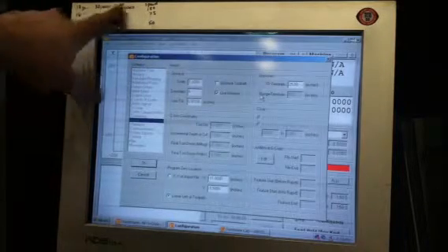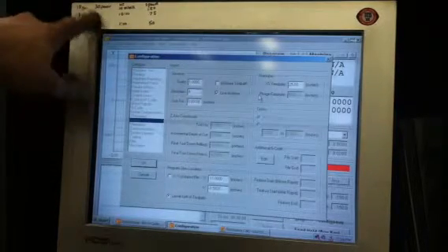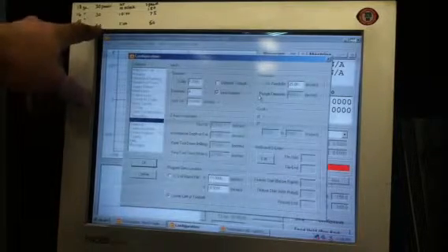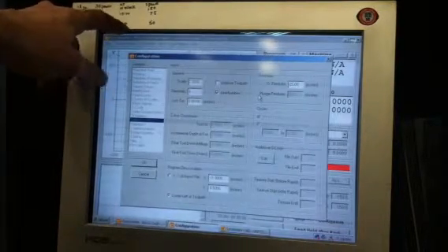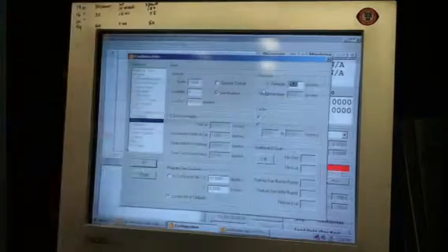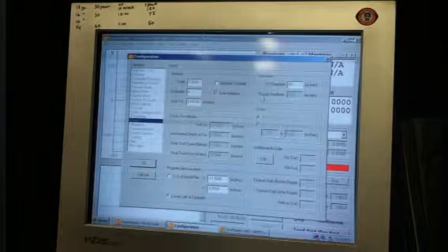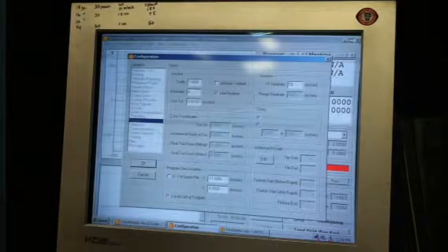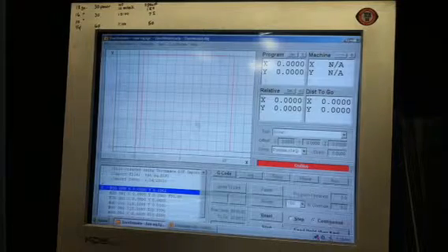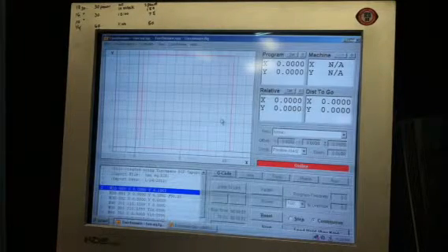Up here I have written on the monitor some different feed rates and powers. Let's say we're going to cut it out of 1/4 inch. I need 60 power, height at 1 o'clock on the height controller, and a speed of 50. So I would select here and go 50. Now my feed right here at the top right, and then hit OK, and it's going to pull up my file, and at this point I'm ready to go.